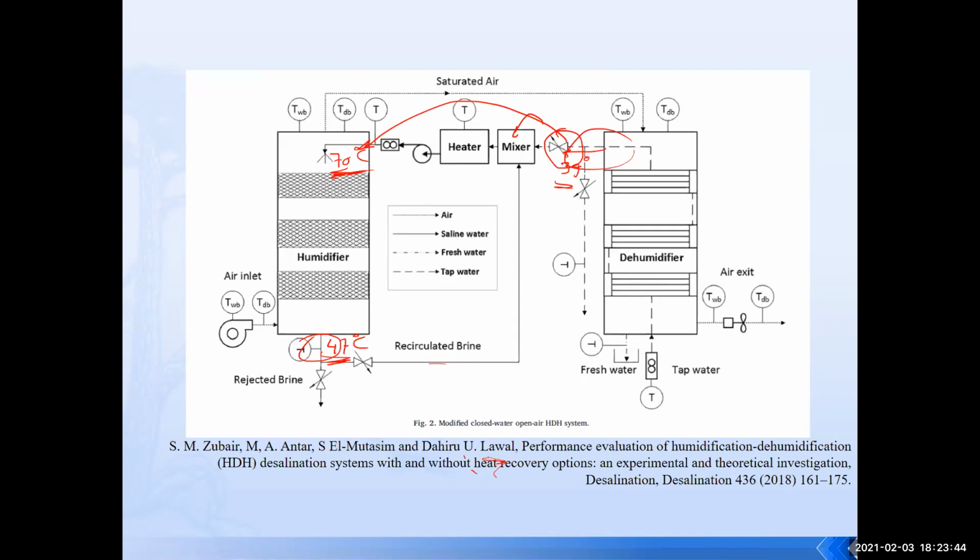And then the question: which is the system that is going to provide us with an inlet temperature of 70 and outlet temperature of 47? Is it related to the effectiveness? The answer is yes. If the system has higher effectiveness, it means I'm going to effectively cool down the water from 70 maybe to 35. In such a case, it does not make sense to use this water, but I should use this one because it's hotter.